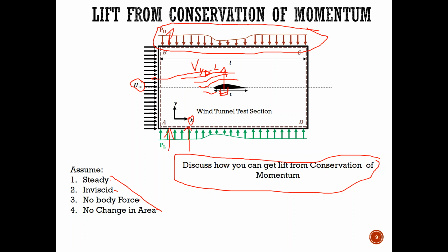As the flow, which curves around the object, meets the tunnel wall, the velocity changes, and that change in velocity translates to a change in pressure. So if there are changes in pressure, it goes for the top and bottom surface. Using this pressure, we can actually determine the lift force acting on the object.